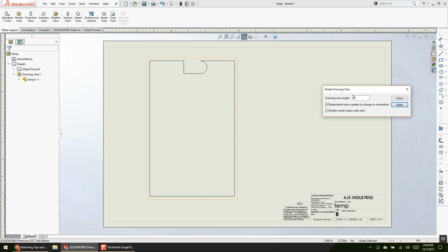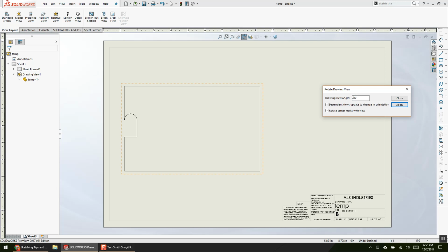This is still, again, limiting my liabilities. And I bring this up because if I have to make my machinist do mental math, transpose the image, flip it upside down or rotate it or anything like that, and a bad part gets made because it was difficult to make based on the information I gave them, it's my fault, right? There's a liability I can limit and say, every machinist in the world makes their parts like this, so I'm going to give them a print that matches their environment.